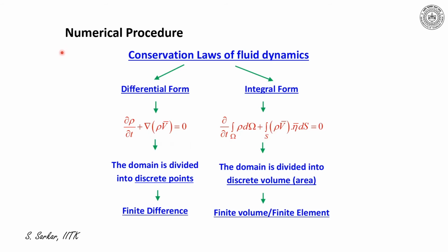I have explained the numerical procedure with the help of a flowchart or flow diagram. What I have written here is that in CFD we deal with the conservation laws of fluid mechanics. Now this governing equation can be put in differential form or integral form. As an example, I have taken the continuity equation. In the differential form, it will be del rho del t plus del dot rho v is equal to 0.